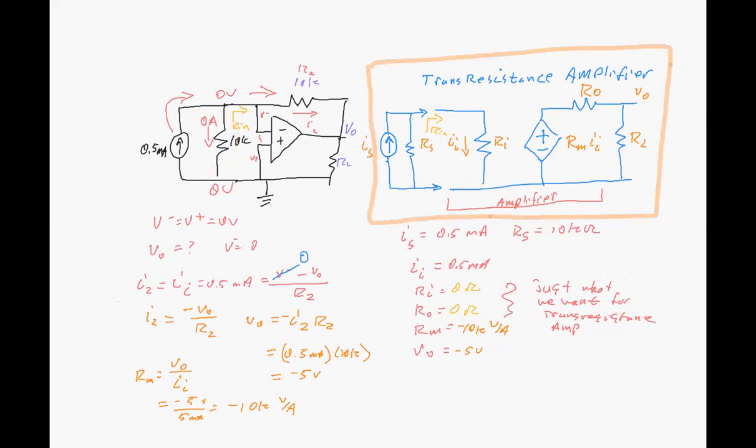And with that abstract model, there's all kinds of things that we can do simply and easily. So a transresistance amplifier, we can perfectly make it from an op-amp using negative feedback. You don't have to think about an op-amp as only being used with a Thevenin voltage input. It could be a Norton current.